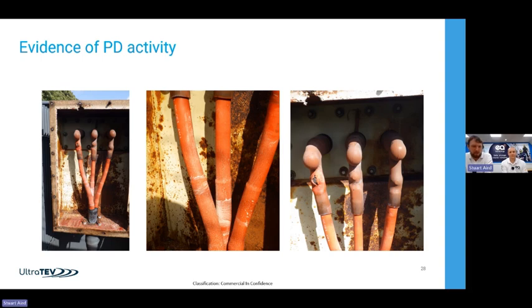Taking the lid off, following the measurement, you're able to see that there's been a lot of deterioration. Probably started around the cable clutch. That's then created an acidic atmosphere inside the cable box, and now the cable boots and everything are all deteriorating with a high amount of rust, etc. So definitely a good find, and something you would have wanted to act upon. And all in all, a relatively easy fix as well at that point, is re-terminating those cables.